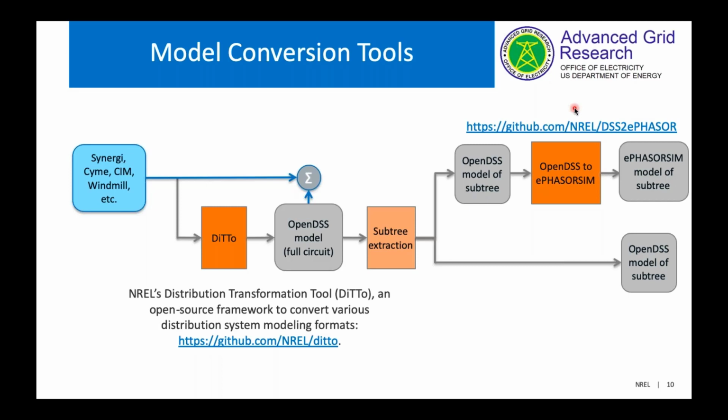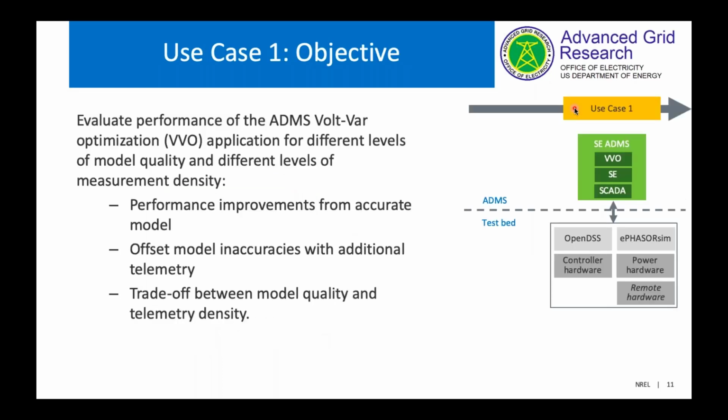So that completes the general overview of the testbed, and now I will go through 3 examples of use cases where we use this testbed. The first one was in partnership with Xcel Energy and Schneider Electric. And the request here was to evaluate the performance of the Volt-VAR optimization application for different levels of model quality and measurement density.